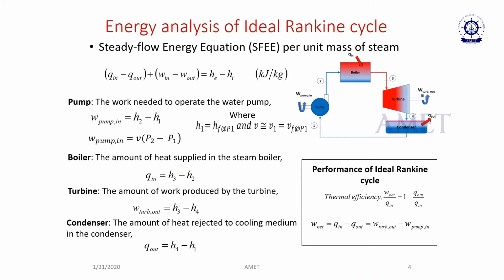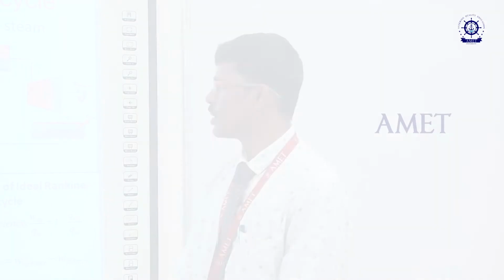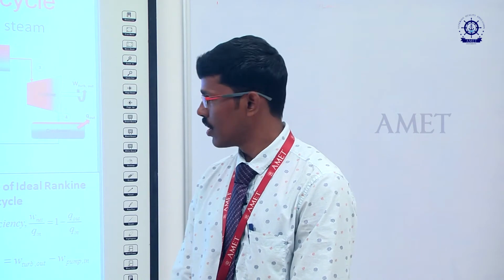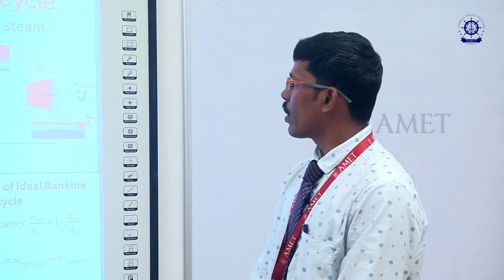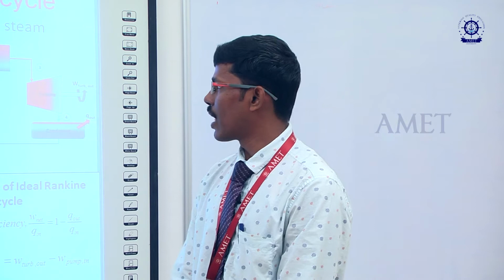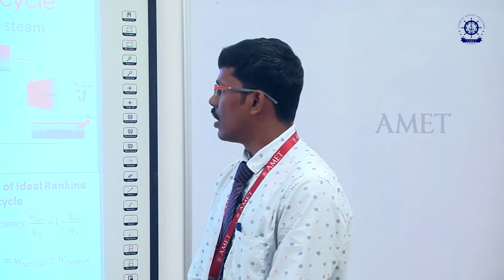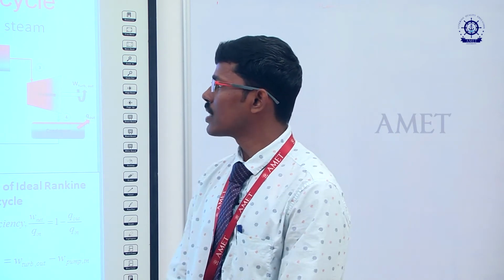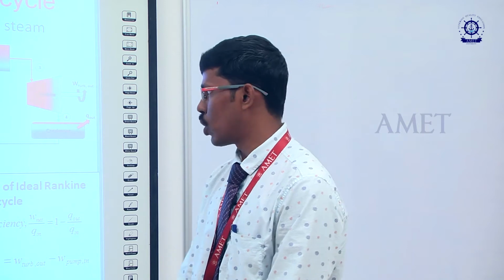The energy analysis of the ideal Rankine cycle. The Rankine cycle has 4 components, which are considered to be steady flow devices. So, we can calculate the energy analysis easily by applying the steady flow energy equation for each component.